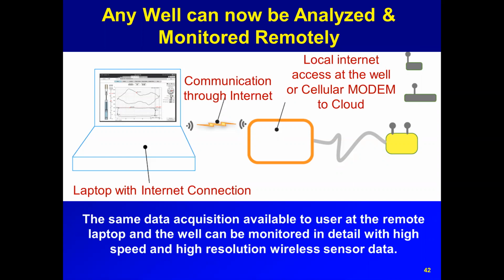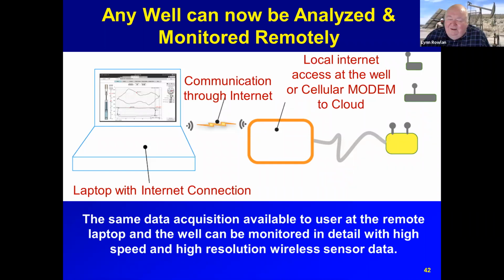Okay, so I lied. We have one more question. Is the Model H able to determine high fluid levels with self-computing? I'm not familiar with the Model H. Carrie Ann Taylor is the engineer at Echometer that uses Model H and does training on it. It has a really good downhole marker method in the Model H to determine distance to liquid. And you can move the liquid levels, and it has the same acoustic trace. So if you shoot a high fluid level, you've got to use a manual method to select the liquid level, and you may only be able to type in the acoustic velocity.